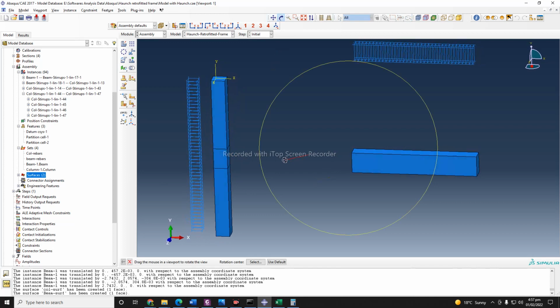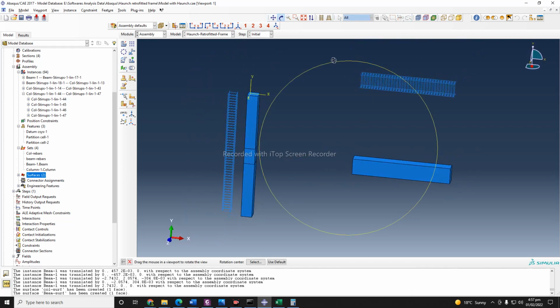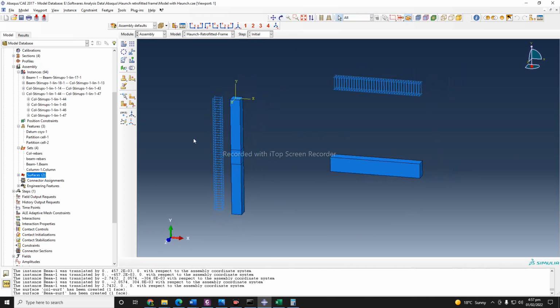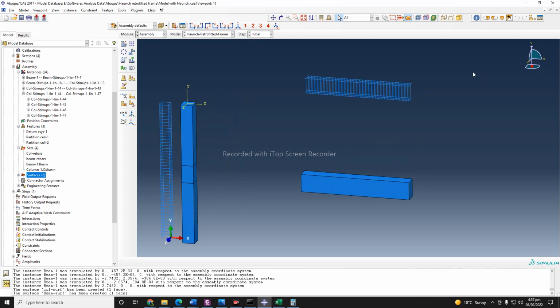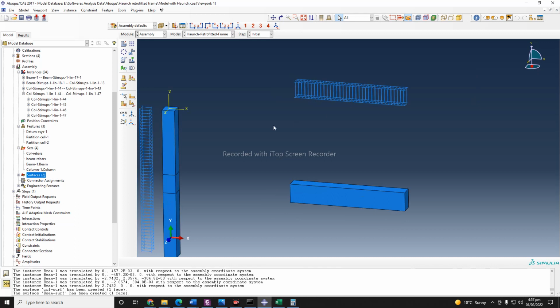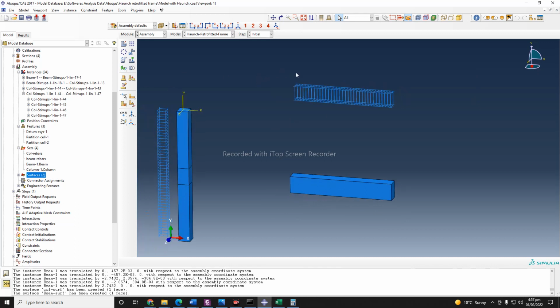Okay, the next thing is that at this moment we do not need anything else, so now we can embed our rebar inside the reinforced concrete section, but at the correct location. For example, you cannot simply select this and bring it here. You need to take the clear cover of the concrete into account. For that again you will need to do some manual calculation and think about the most suitable location. For example, as I'm doing it here, you can choose the translate instance option. Done.